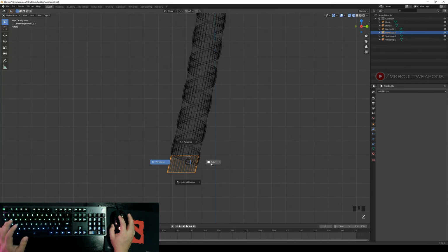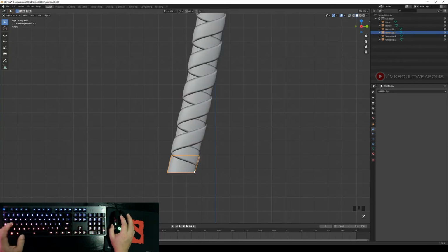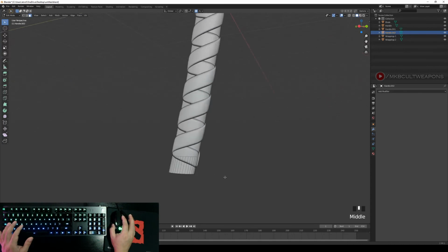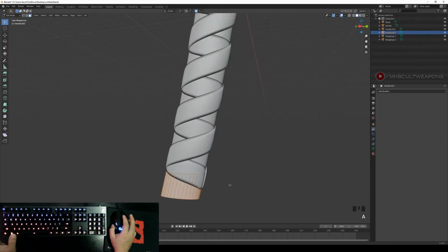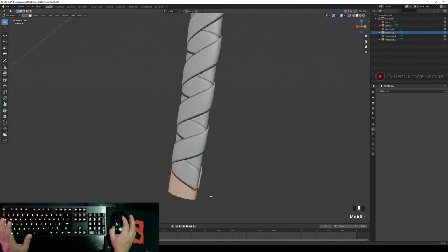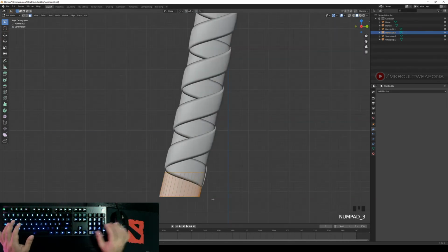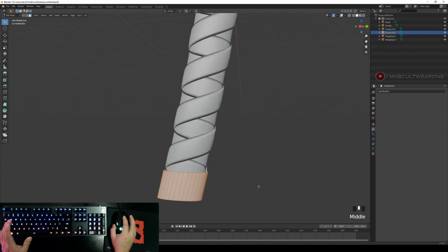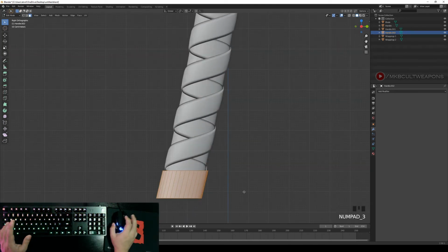Let us go to solid mode again, then let's just scale this up, maybe by pressing S. Or rather, let's just go to edit mode first and press A to select everything, and press S. Let's just remove the proportional editing because we don't need that yet. Again, press S up to this point. Yep, yes, that's good, I guess.